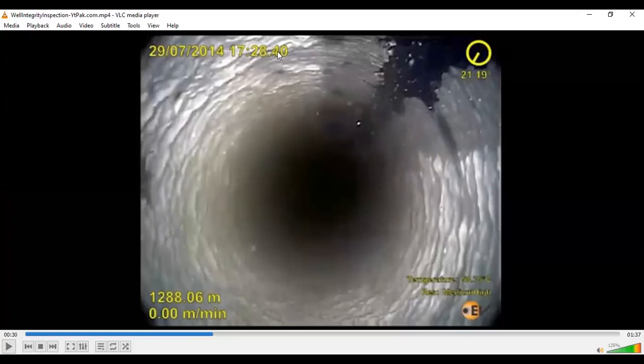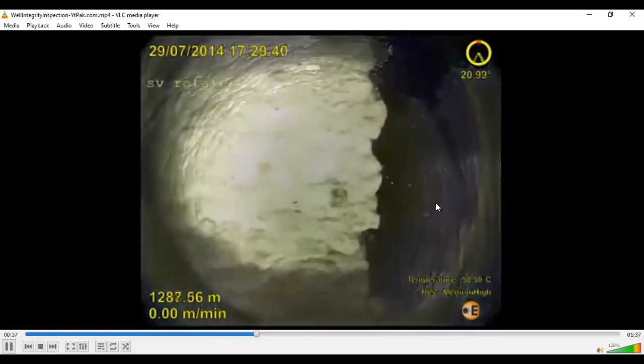Look at the area around. It's not clean. There's a lot of material which has accumulated around the wellbore, which has reduced the diameter of the pipeline. Secondly, there is some leakage. That's why they are running the camera downhole to check where the leakage is, and then they have to fix that pipe. For a larger diameter completion, there is significant scale buildup, and debris can also be seen flowing into the well at this point.